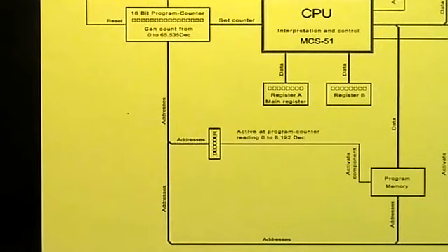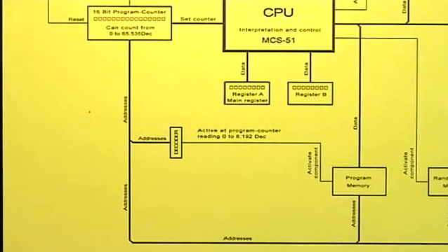The CPU's MCS51 core interprets this binary value to ensure that the program counter is set to a specific value after execution of this instruction. This executes a program jump. How far and where the jump should go is written in the two memory locations that follow this instruction. The MCS51 core also knows this because of the previous instruction.